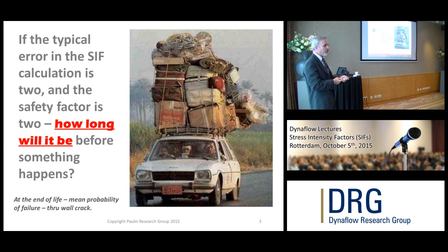Accidents waiting to happen in piping systems are fatigue. Fatigue failures occur when the stress is right at the allowable, or right at twice the allowable, twice the safety factor. Accidents occur at the end of life. So the problem with piping is that somebody makes a mistake, 5 years into it, 10 years into a 40-year life, you think everything's fine.